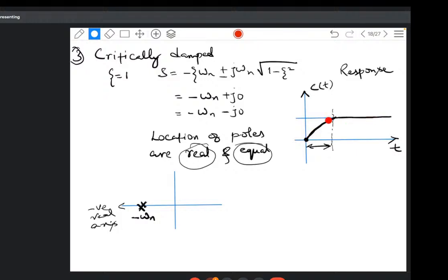But here, no oscillation is seen and it settles to the steady state and remains there. What is the reason for that? Because we have provided damping which is sufficient to kill all the oscillation. You have provided the exact damping to the system which has killed all the oscillation. So this is my pole location and this is my corresponding response.